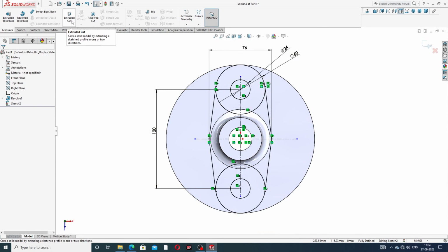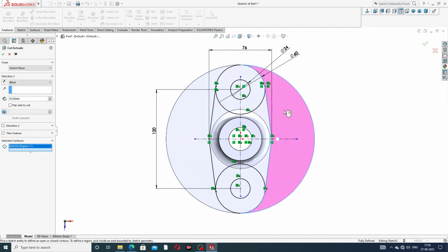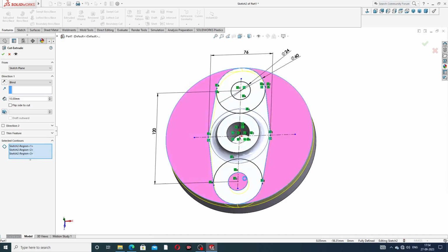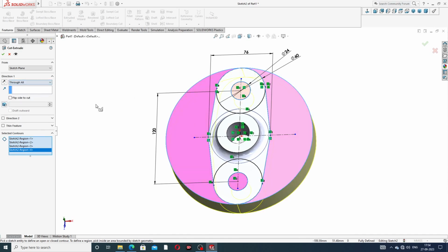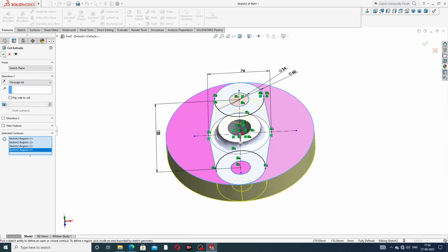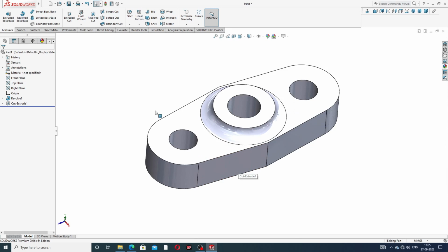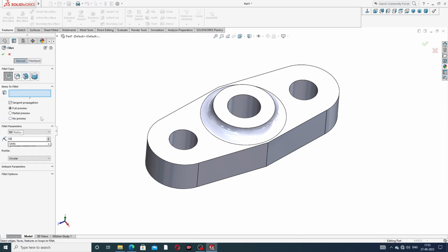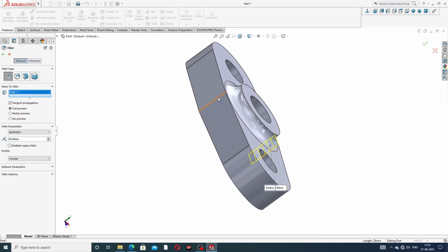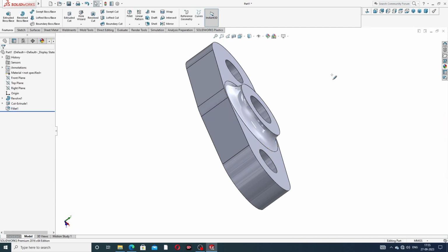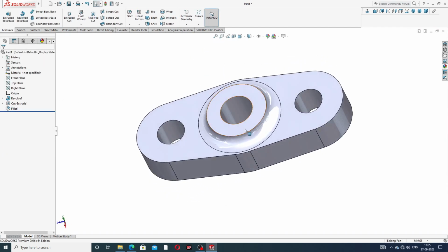and going to this extrude cut and apply, the extra portion is deleted here. Okay, and select this and this. Okay, and through all, extra portion is deleted here, and okay, this is perfect. Okay, and again select a fillet, use here 50 millimeter, and both edges are selected here. Okay, and click OK. Okay, this is perfect and correct.